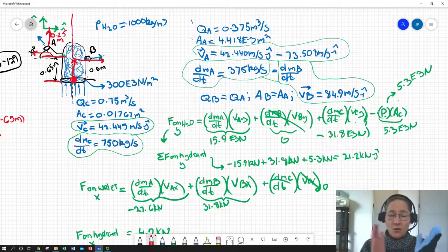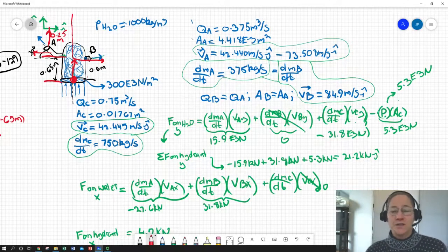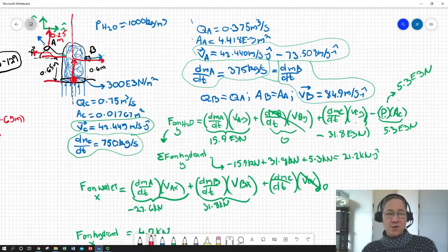Again, if you're talking about a reference volume and an elbow or a pipe, you've got to assume that force is being applied maybe uniformly along the walls of the pipe or the elbow, and so you'll look at that entire coupling or pipe as having a force acting uniformly on it, maybe at its centroid typically, in its orientation. And again, that's very similar to the example given in the Hibbler 14th edition text. But in this case, the water comes in, you can kind of think of it as stopping. So I wanted to give that as a clarification because it is a little bit different,